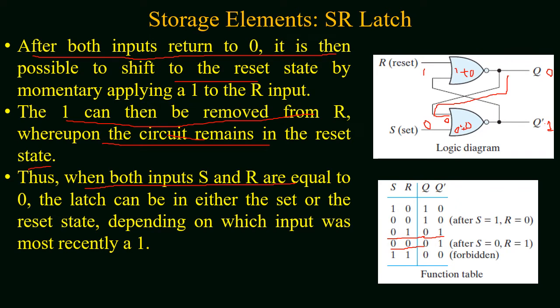Thus with both inputs S and R equal to 0, the latch can be either in the set state or in the reset state, depending on which input was applied most recently.